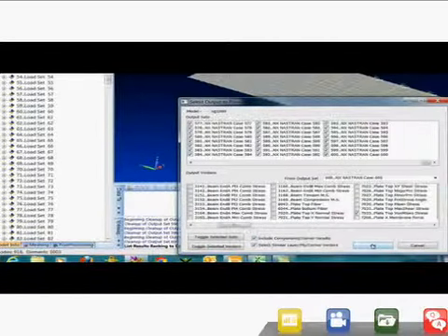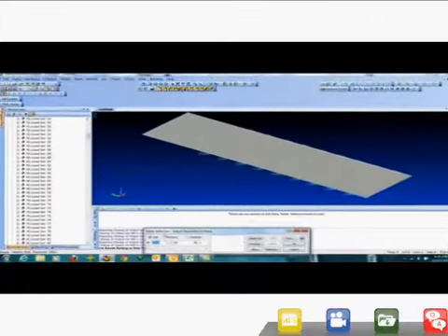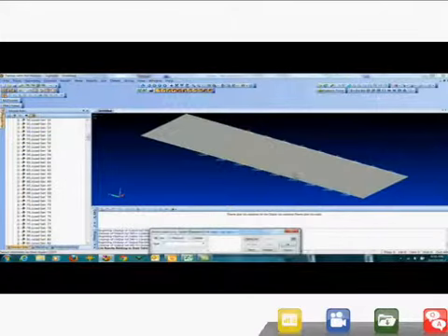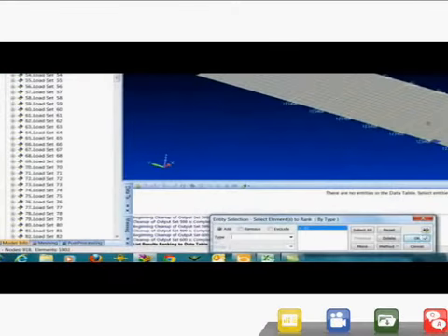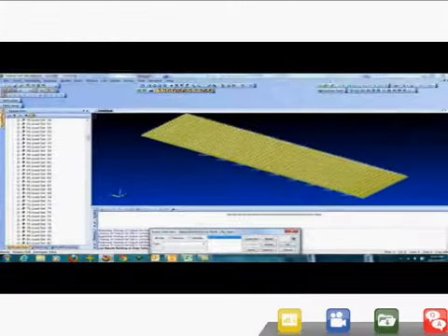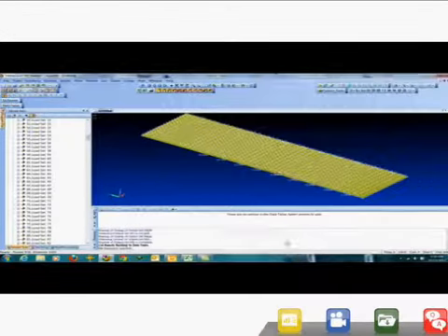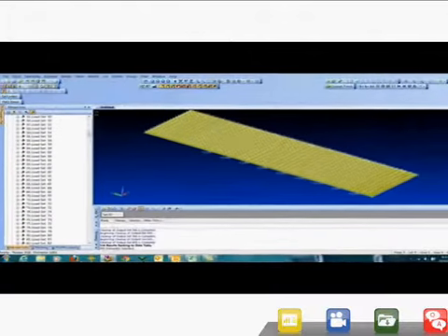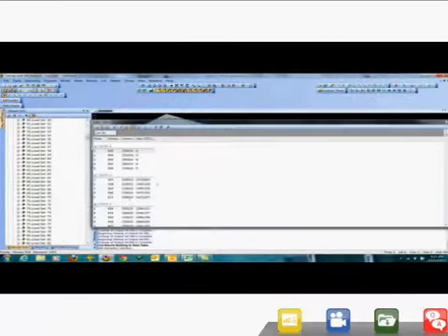So in one shot here, we're going to go grab all the maximum von Mises stresses, and it's asking me what elements to pick, and I can just say by type. And go pick one plate out of the model and just say more. Just make sure we're getting them. There's all our plates. Say OK. It's cranking through all 600 sets for 850 elements. There, the data is already in.